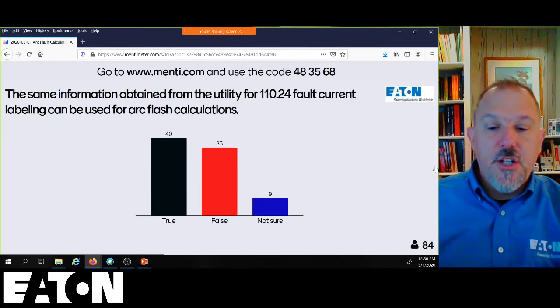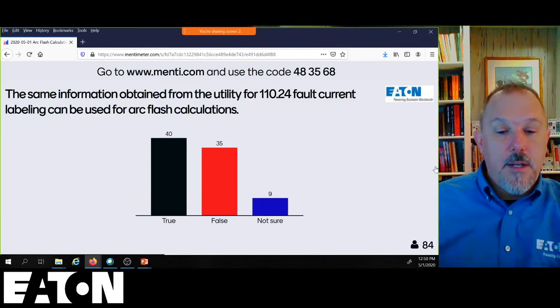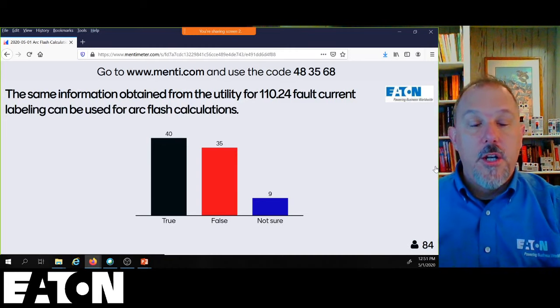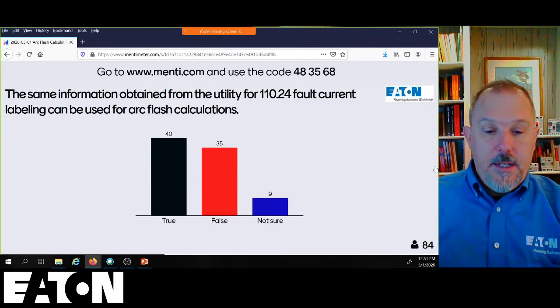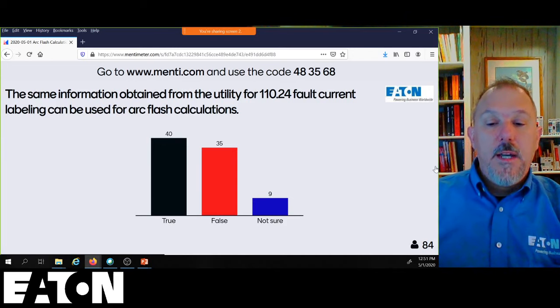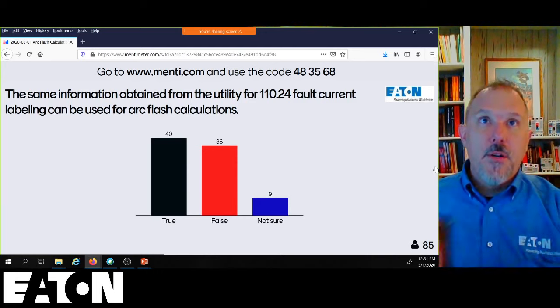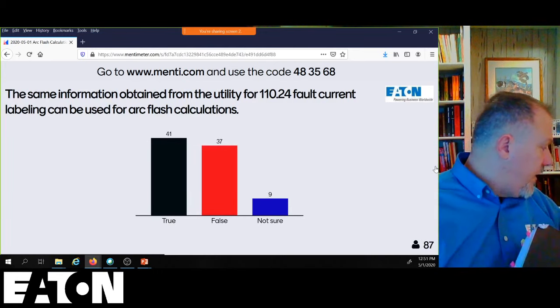And there's an informational note. The available fault current markings addressed in 110.24 are related to required short circuit current ratings and interrupting ratings of equipment. NFPA 70E, Standard for Electrical Safety in the Workplace, provides assistance in determining the severity of potential exposure, planning safe work practices, and selecting personal protective equipment.